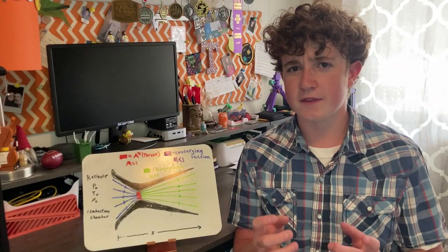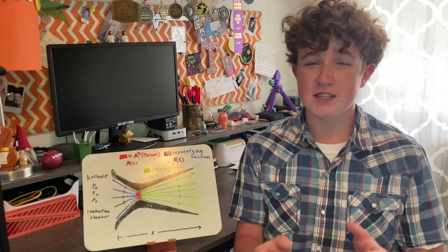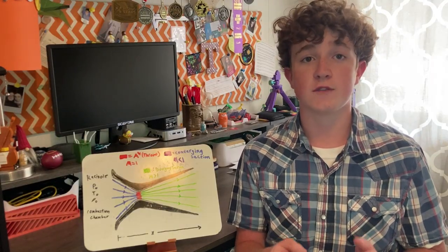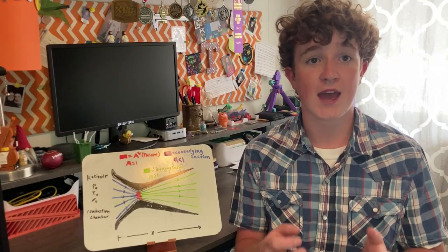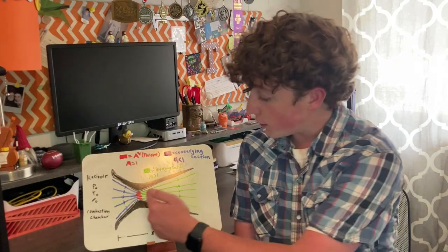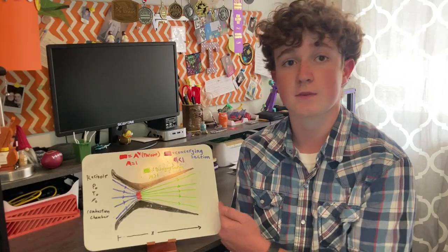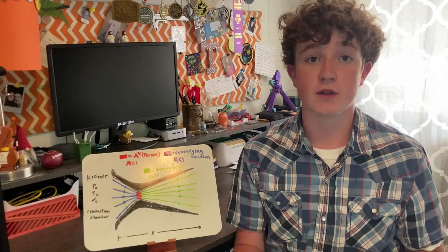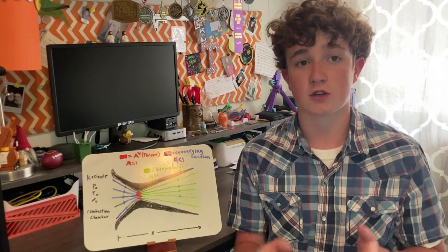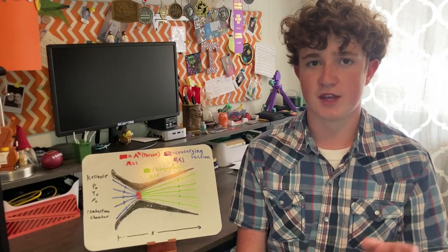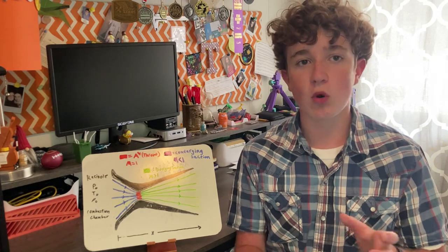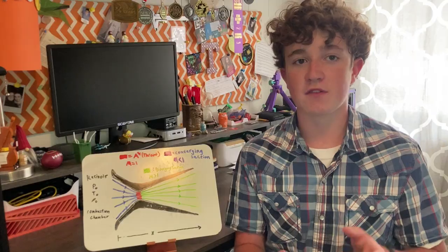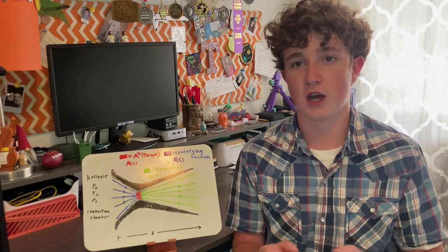Now here's where things take a weird turn. Because of the interesting physics of supersonic flow, in order to further increase the fluid velocity, the cross-sectional area actually has to expand from the throat. We can see that here with those green lines. This is because the rapid changes in density from the fluid cause the velocity to continue to increase. I'll explain this more in depth a little later. Think of it as there is more room for the gas to expand and pick up speed. This increase in area after the throat is called the diverging section of the nozzle.